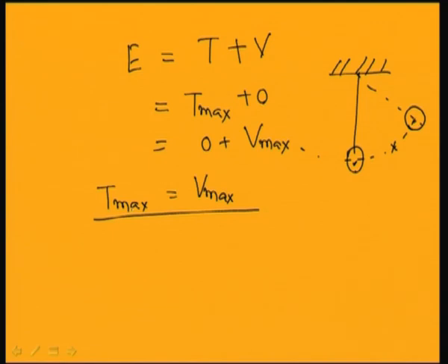So, from this, let us assume a function, a certain mode. If you assume a certain mode, that is Z, let Z equal to, I am assuming in this form, Z1, Z2, Zn. So, let me assume this mode. If I substitute this in the kinetic energy and potential energy, I can write the kinetic energy term. You know the kinetic energy can be written as half V transpose mv. So, I can write T max, maximum kinetic energy, equal to half Z transpose m Z omega square.